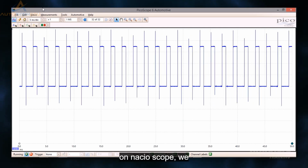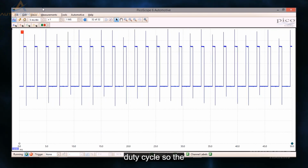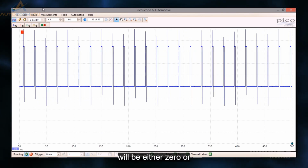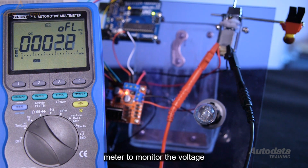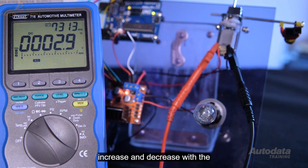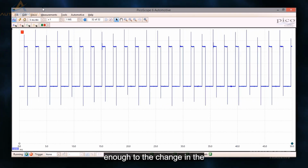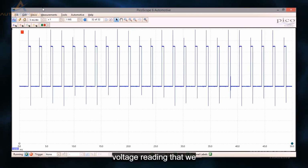When looking at this on an oscilloscope, we can see the PWM control changing the duty cycle, so the motor speed changes. But if you look at the supply voltage, it remains constant. It will be either 0 or 4 volts. This time, I'll use the multimeter to monitor the voltage. We'll see the voltage increase and decrease with the motor speed. The reason for this is because the multimeter cannot react fast enough to the change in the duty cycle control. It displays an average voltage reading that we can see.